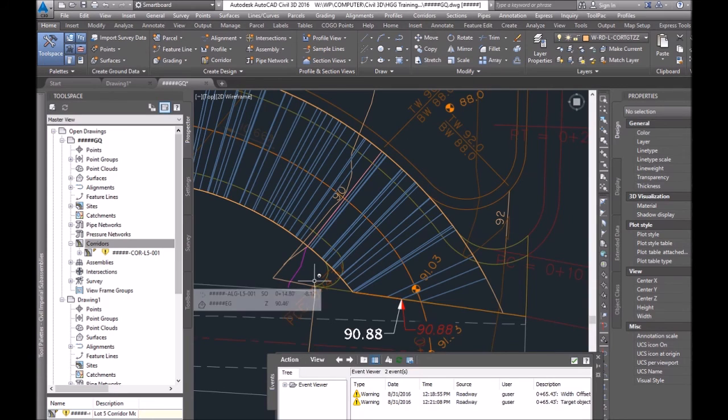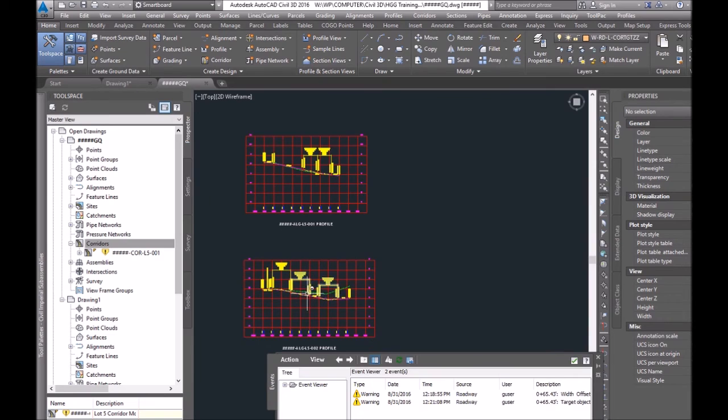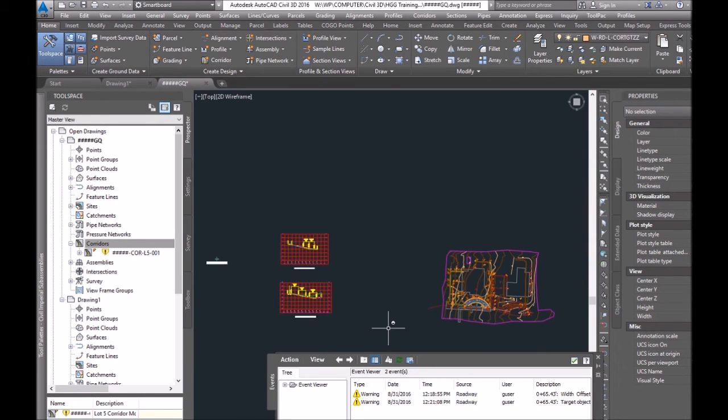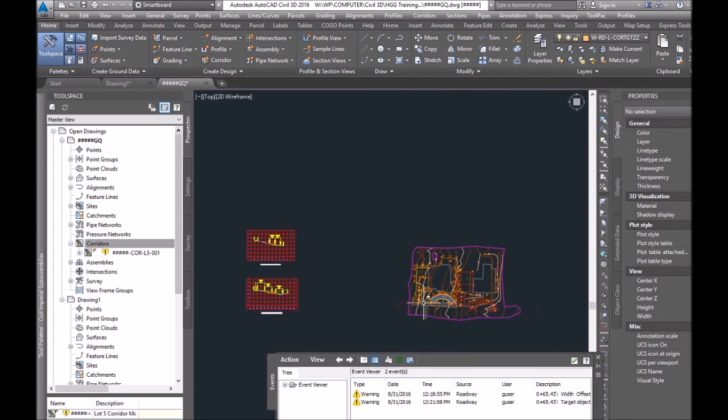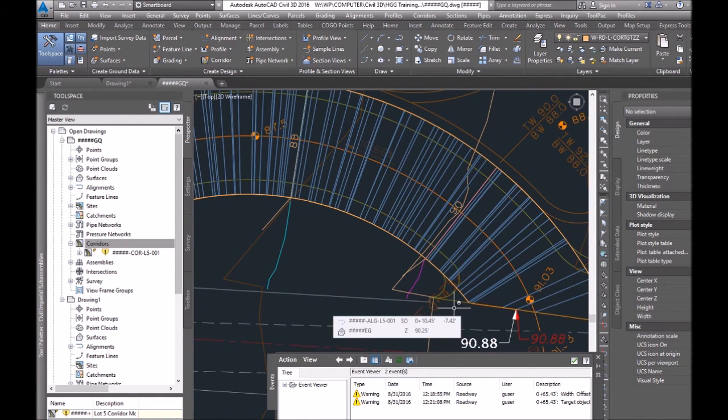But if it was a larger project where you needed a curb return over there, I would put in an alignment right here with its own profile, just like what we have created over here, and have a flow line profile. That way, if you guys needed to stake something as well in the future, you can always use it for reference. It's been working pretty well with Avalon, even though there were mistakes that we made in the flow line profile.